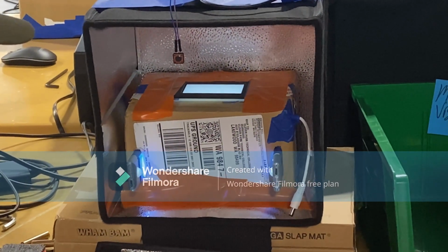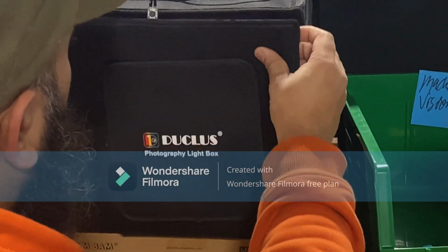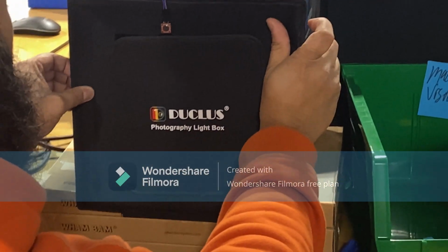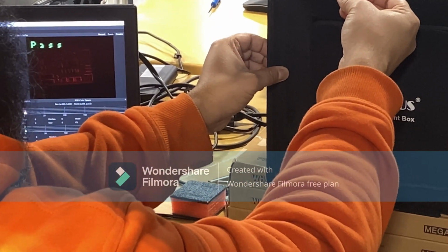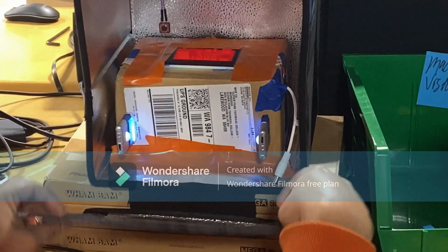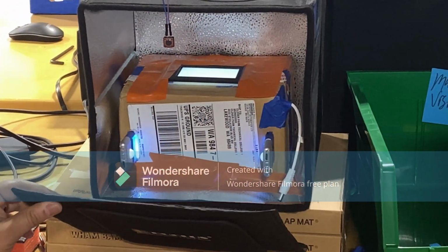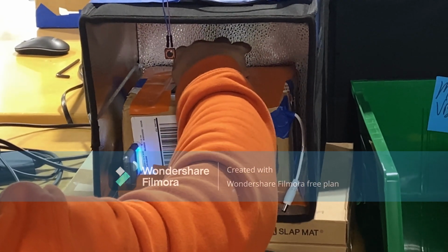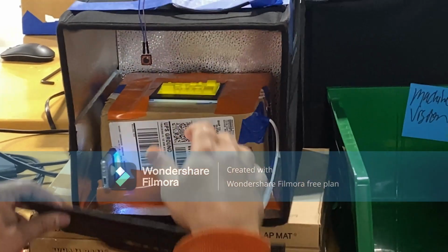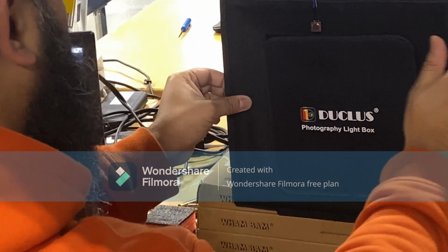light box. As you can also see from my classmate's interaction with the vision system, this system contains a human-to-machine interface and will require the operator to carefully place the part into the fixture, close the door, and press the button to take a snapshot. It will also be the job of the operator to maintain the system by removing any debris inside the light box and maintaining and replacing the camera lens when needed.